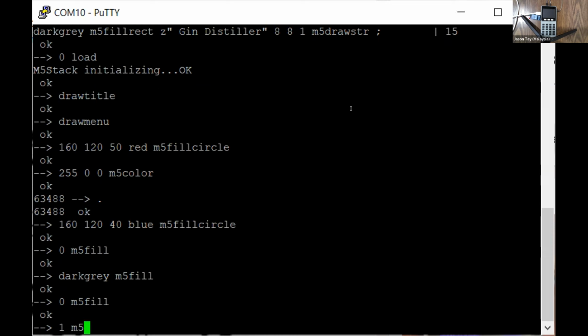So I think one of the things that you will experience if you try to do embedded displays is that we have such an assumption that fonts will always be around, but that's not really the case with embedded systems. Usually there are no fonts, and you have to decide how you're going to represent and store them in the ROM and so on.